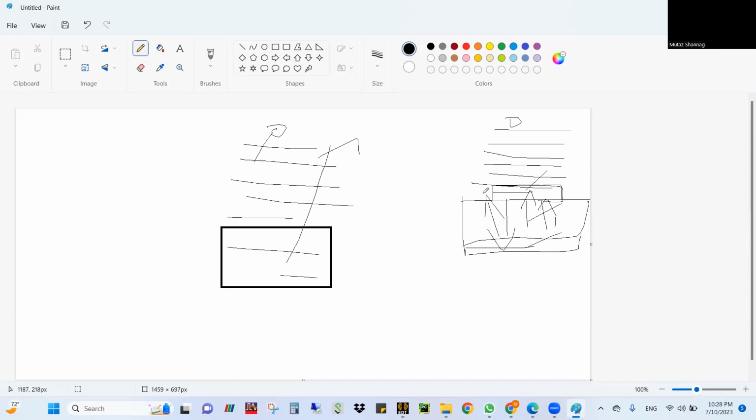So when it hits, there is edge diffraction that will happen, then it will impinge on this. It is a ground plane, or we can say a reflector, and it just reflects back. So the moment it enters this one, this is the boundary, basically, it gets inside somehow. And then comes back. So it will create a delay, basically. A delay, right? We can call it a phase delay. In other words, called phase. So how am I saying delay as a phase?